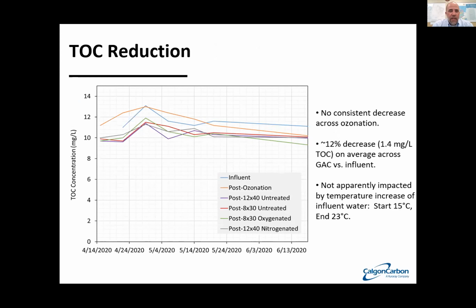So TOC reduction, this was somewhat confounding. Perhaps it makes sense in the context of the wastewater treatment system, that we would have seen more degradation in that system, or excuse me, that the compounds coming into our system were more recalcitrant. We did not see a large decrease over time, an average of a 12% decrease, and maybe some temperature impact where you see lower levels coming in, but not something I would say was a large TOC reduction.